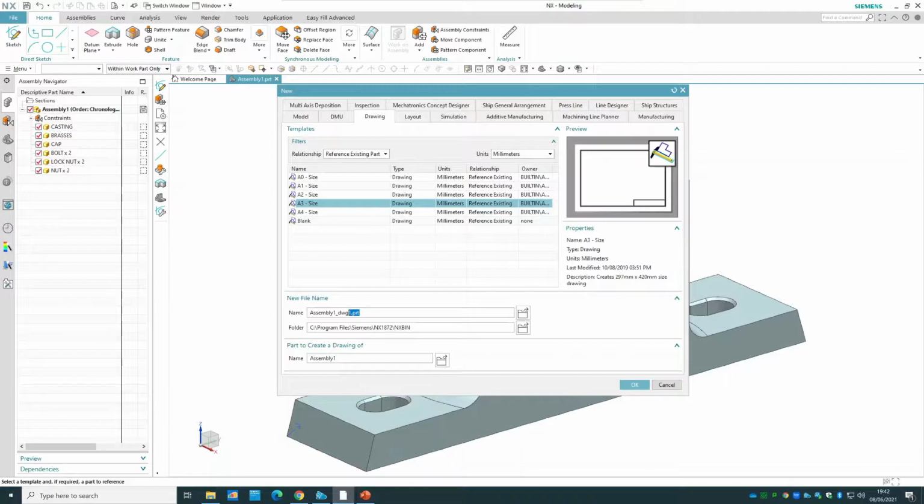But something is really important. This file is still a .prt file. So all of the files you generate through the Siemens NX have the .prt extension by default. So it's really important to save it in your local drive again. Usually we'll save it in the same folder that we already drew the file in, so we never have any problem loading the actual file, because you will have some sort of linkage with the main part you have. So same as assembly, it's better to save it to the same folder that you have. And then you click on OK.